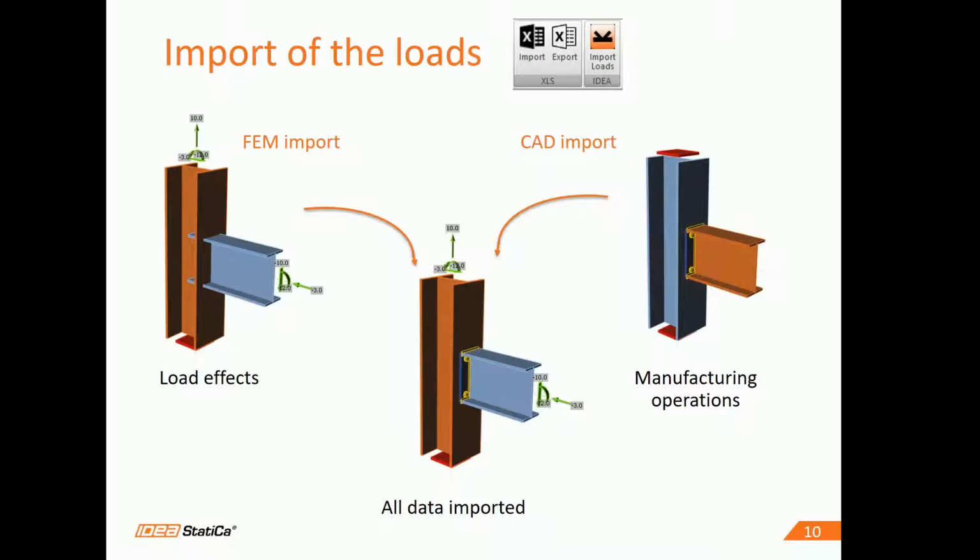A really important feature: we prepared a new way to import the loads. In past versions we had, and we still have, the possibility to import load effects from a previously prepared Excel spreadsheet. Now we can import loads from a project that we did before or imported. This allows us, for example, to create an import from a finite element analysis tool, and we get the load effects.